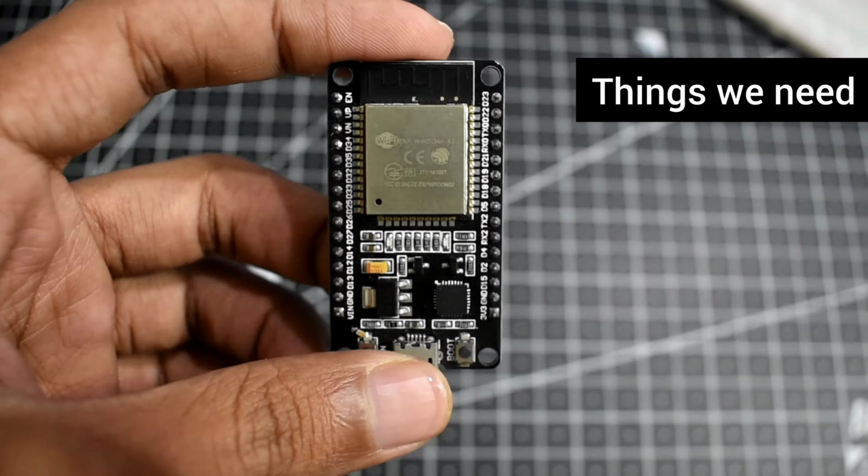1.3.8, that's absolutely right. Now we need to define the sensor pin. So define DHT sensor pin, and the sensor pin that we have chosen is pin number 4. We also need to specify the DHT sensor type, and the DHT sensor type I'm using is DHT11. You can choose whatever you have with you. So that's it.